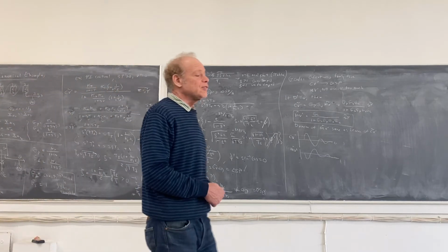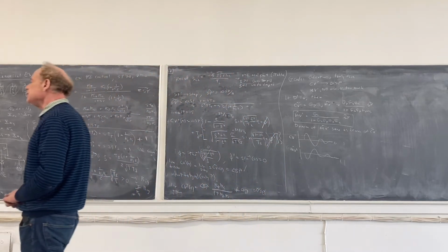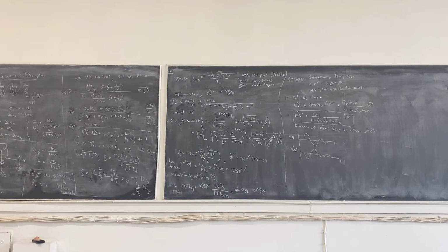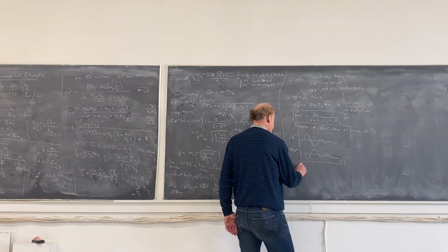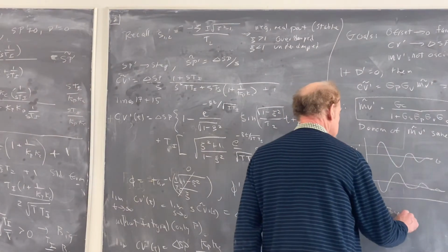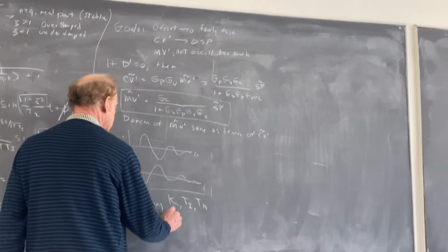So what am I saying? The PID controller predates von Neumann. So why did they choose the PID controller? They chose the PID controller because it frequently does a very good job if you have good values of Kc, Ti, Td. If you don't have good values, it sucks, to use modern parlance. So you have to do a good job of finding Kc, Ti, Td, and that's called the tuning problem. So finding, optimizing Kc, Ti, Td is called tuning the controller.